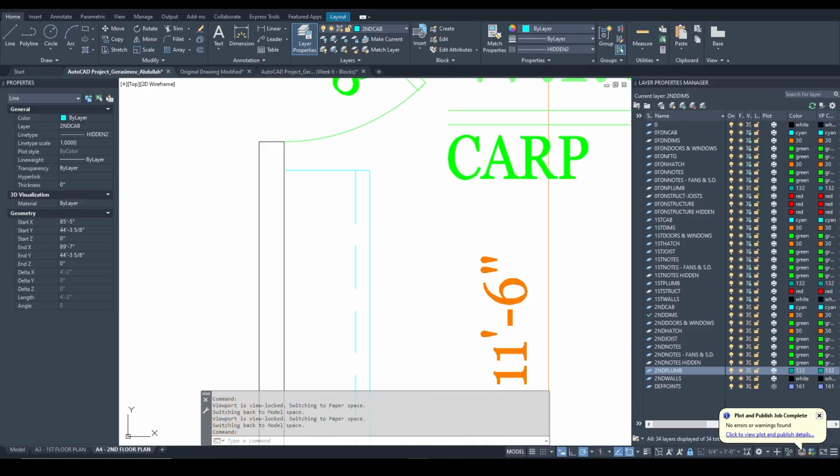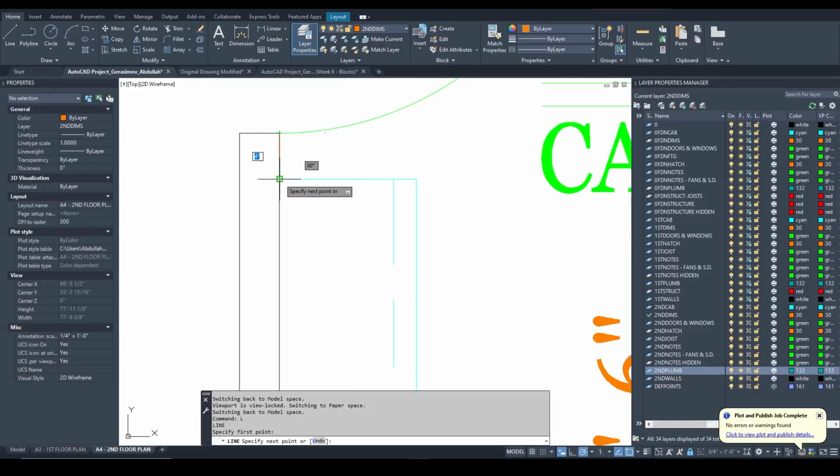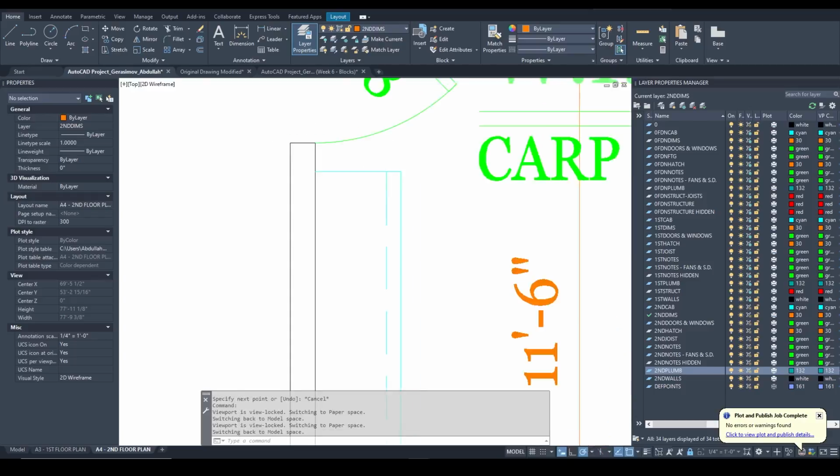Here, there's no specific distance between the door and the shelving, but I would keep it somewhere around 4 inches. That would be solid enough distance, because we have to take into account the casing for the door, which would be anywhere from 1.5 to 4 inches.